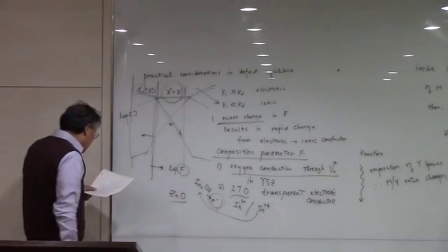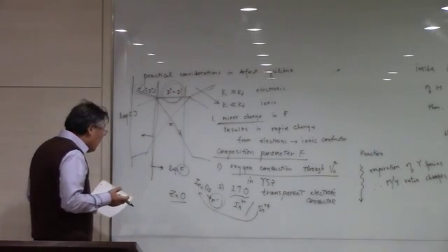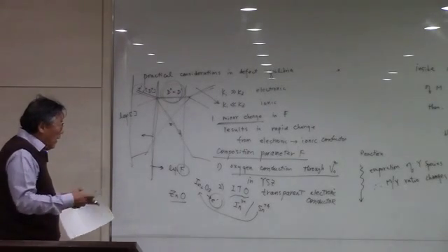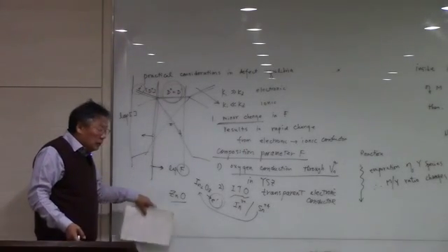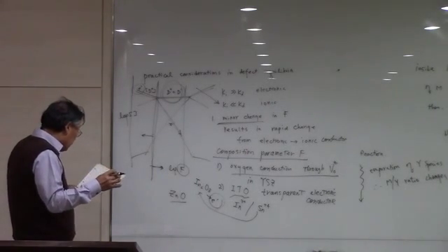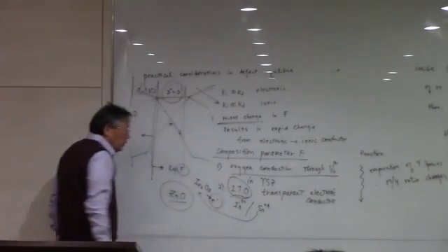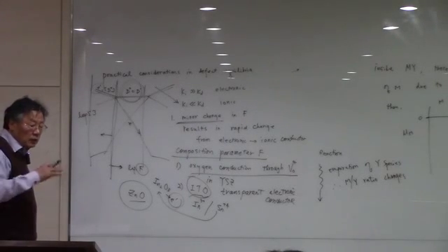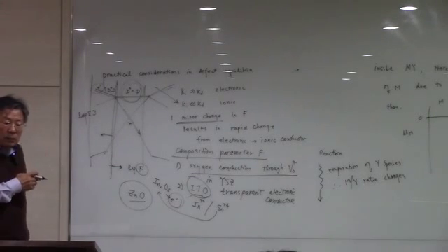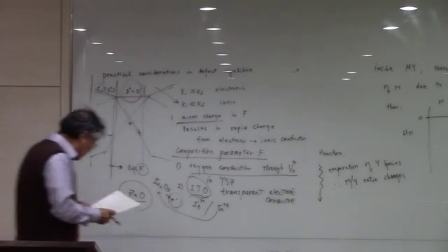In this zinc oxide, you're going to have zinc vacancies, which is related to the free carrier generation, and then that is going to be used as a conducting material. Okay, so zinc oxide and ITO are two major materials to be used as a transparent electronic conductor, and that is very, very important in the flat panel display devices, all the display devices.